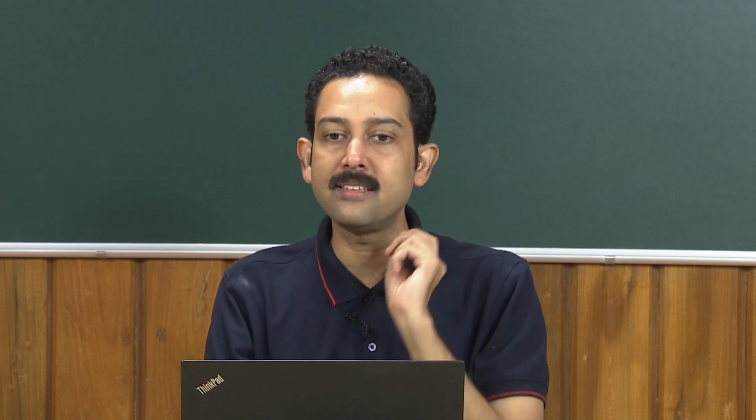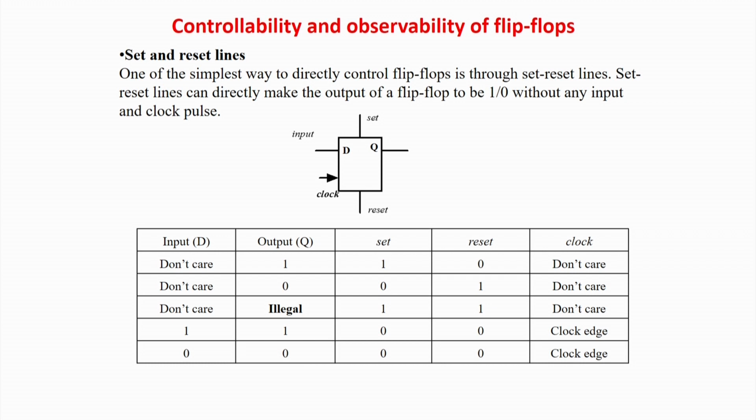The problem compared to a combinational circuit is that you require more test patterns to test a single stuck-at fault. That is where optimization comes into the picture. Even in a very small circuit where you have 100 faults, to test a single fault if you require 10 or 20 patterns, to test 100 faults it will be on the level of 1000 patterns, which is not at all possible even for a medium scale integration circuit. Forget about NOC and SOC.